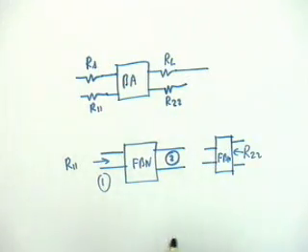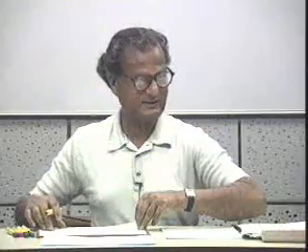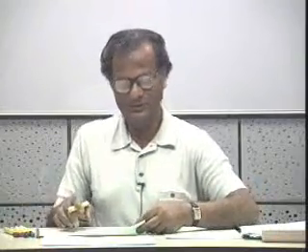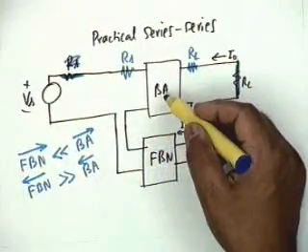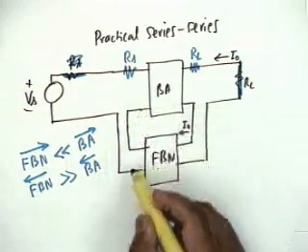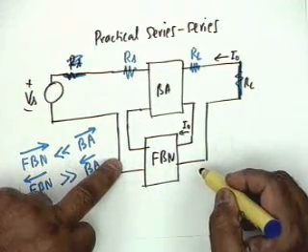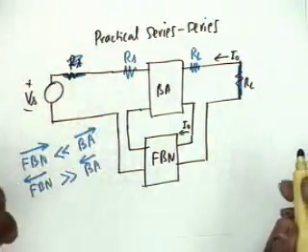Okay. Alright. So we have identified the A circuit, the B circuit, the beta circuit. Is this point clear? Okay, what I wanted to do is to include the impedances of the feedback network in the basic amplifier. Now how do I do that? If there comes a series impedance here, I will put it here. How does the series impedance come? Obviously this is the impedance measured here with this port opened. Why? This is because the appropriate parameters here are the Z parameters, small z, the impedance parameters.